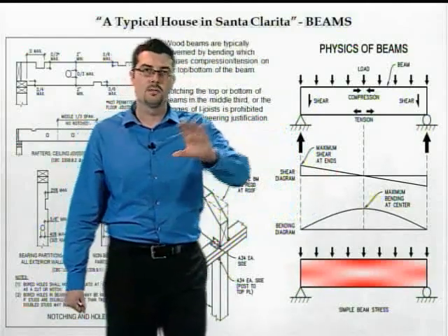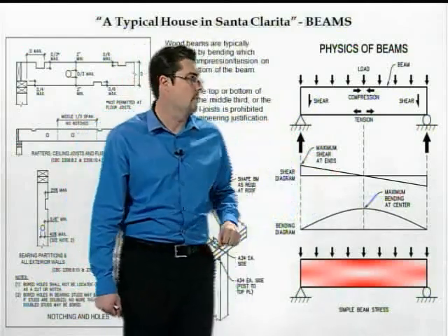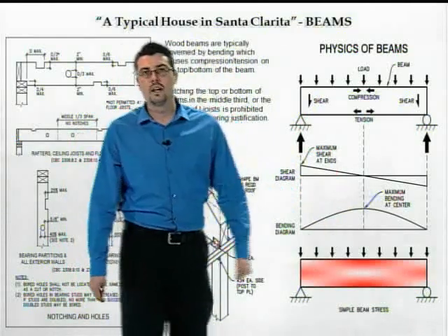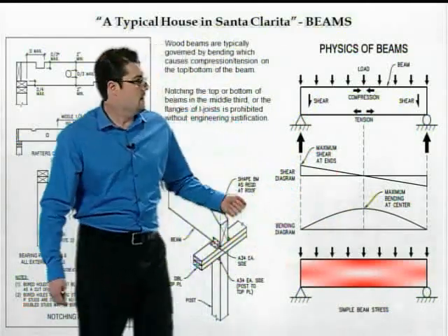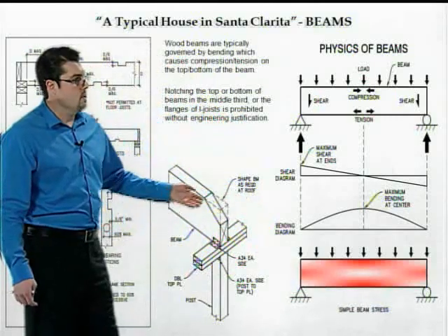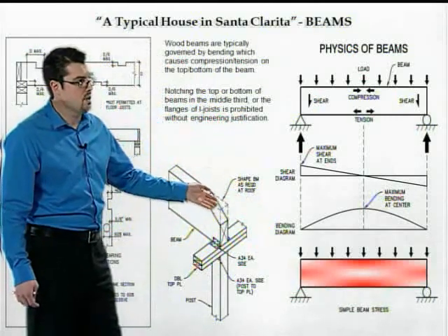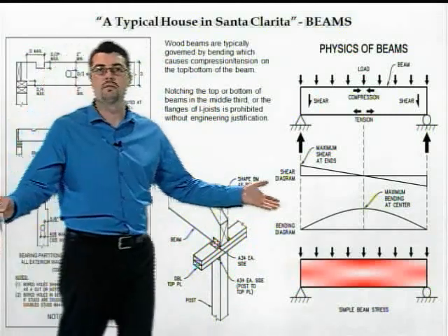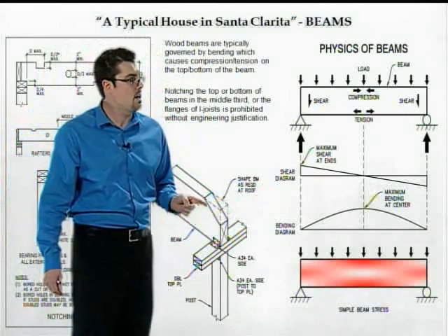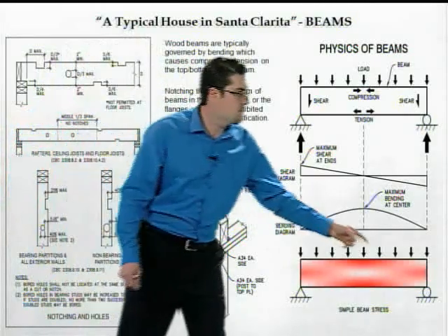We're going to see some examples later of why that's extremely important. Shear forces are usually not governing, and so in most applications, like at a roof beam, you can actually cut out a portion of the beam, and the beam is still fine, because the shear is not what controls. The maximum force in the beam is not here at the reaction, it's here in the middle.